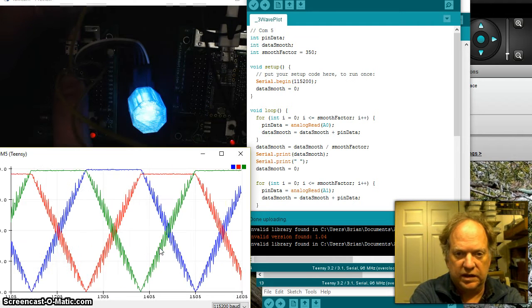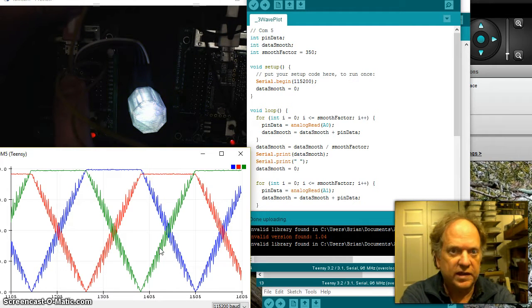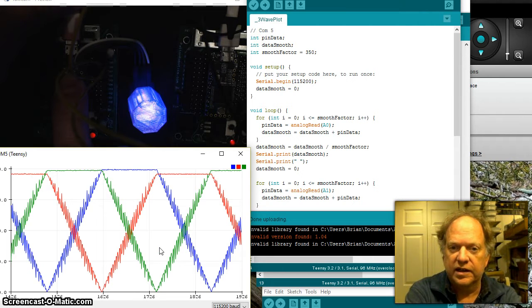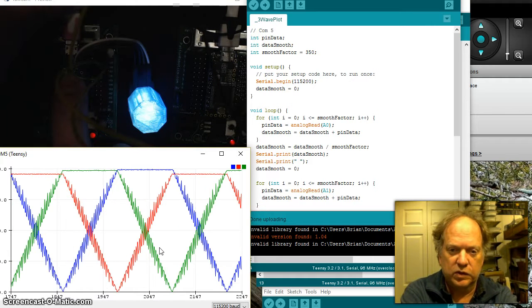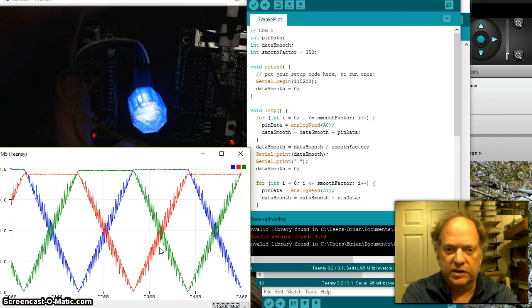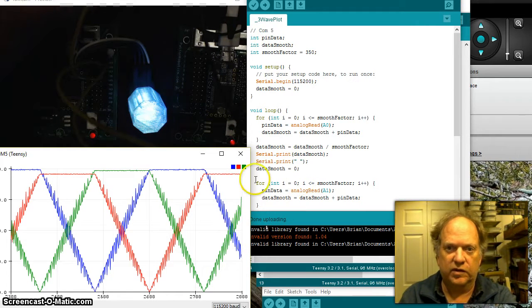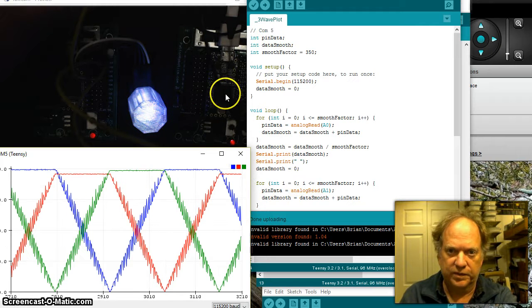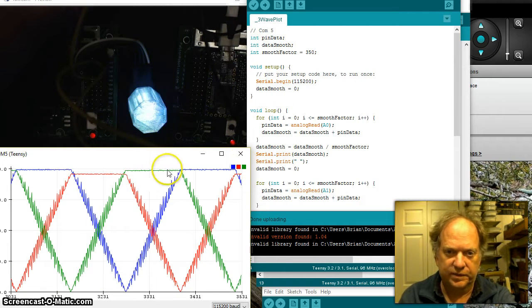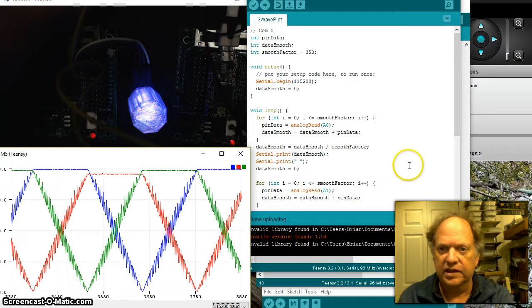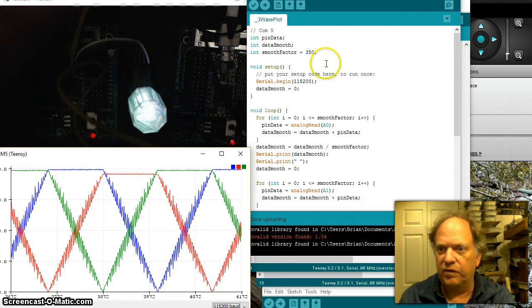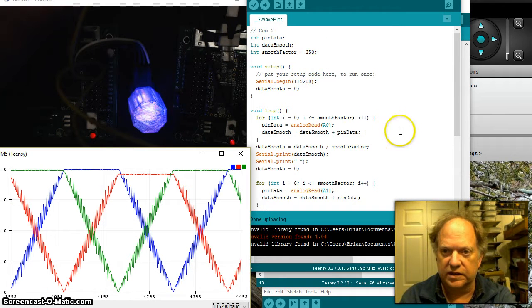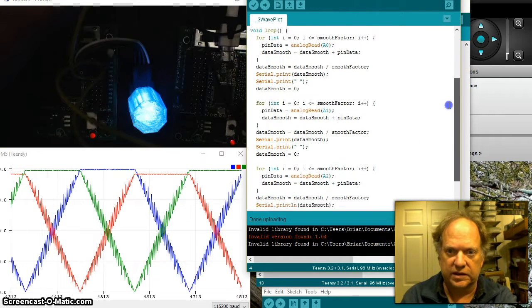All right. So it appears as though, yes, you can get rid of the delay, but you still have to put in something that consumes that amount of time, at least in my circumstance, transferring the data from one of these Arduino Teensies, or the Teensies that are Arduino compatible, through the serial monitor up here to the graph display. And it appears in my case to be the magic number of about 400, which seems to balance out nicely, and I get a seemingly pretty good piece of data.